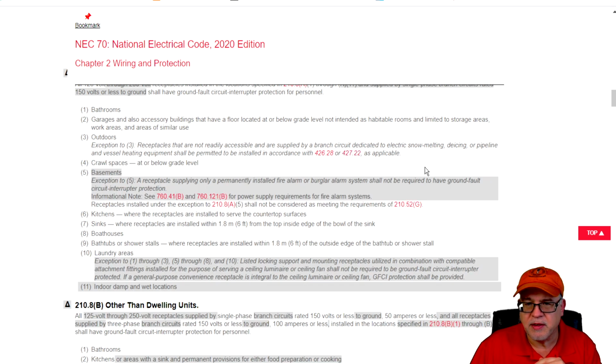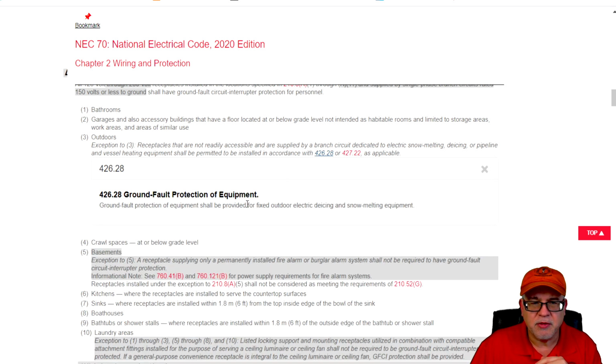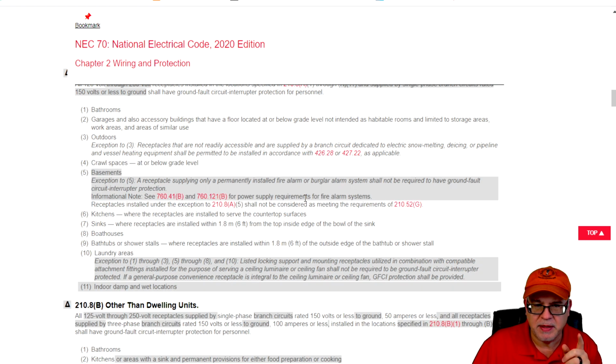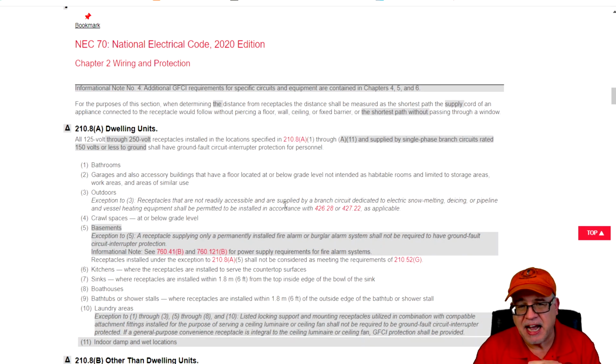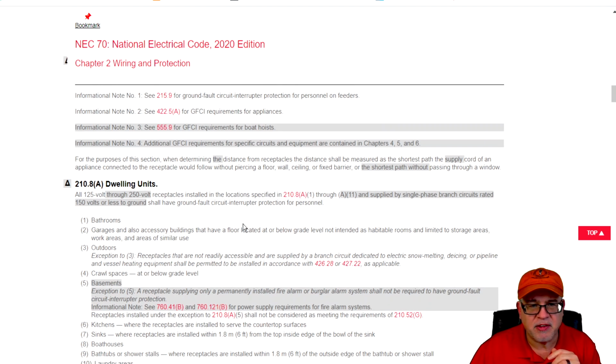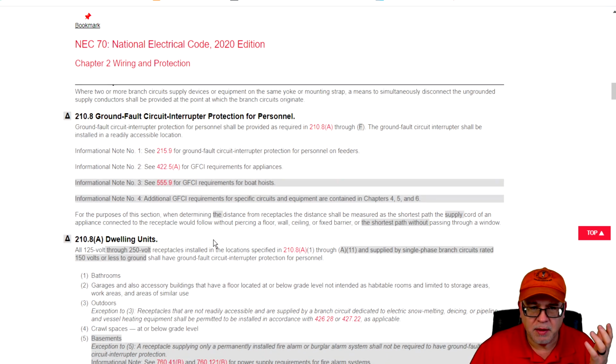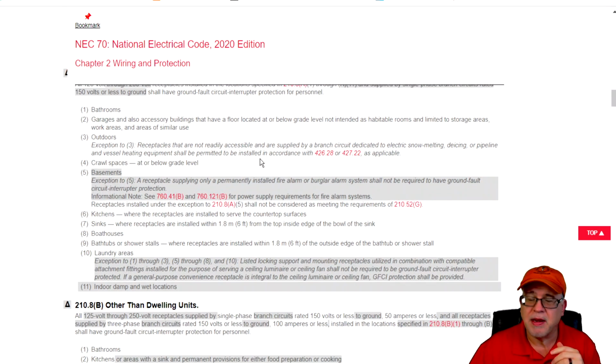So you see the point in difference here. I'll go back here and you see ground fault protection is different, at a higher threshold level than what GFCI protection would be, which is a 5 milliamps nominal value. So there's a slight difference in the requirement there. As you can see, this is ground fault circuit interrupters for protection for personnel. So they don't have to be GFCI devices, but they have their own requirements for GFP, ground fault protection as well, that's covered in those other areas.